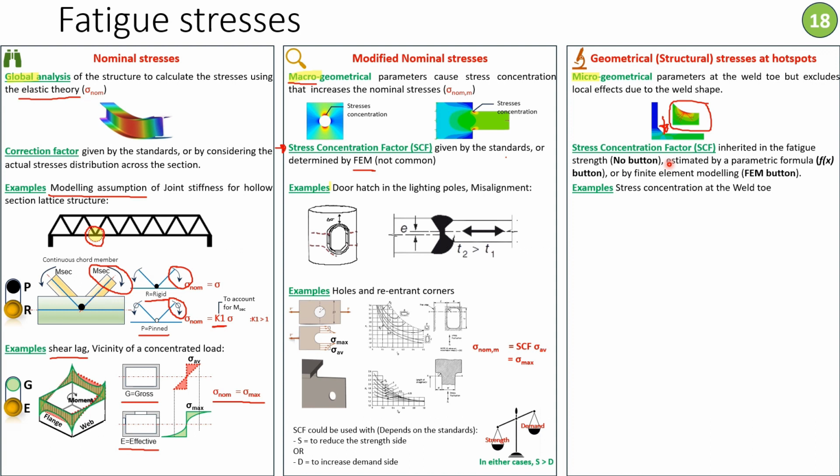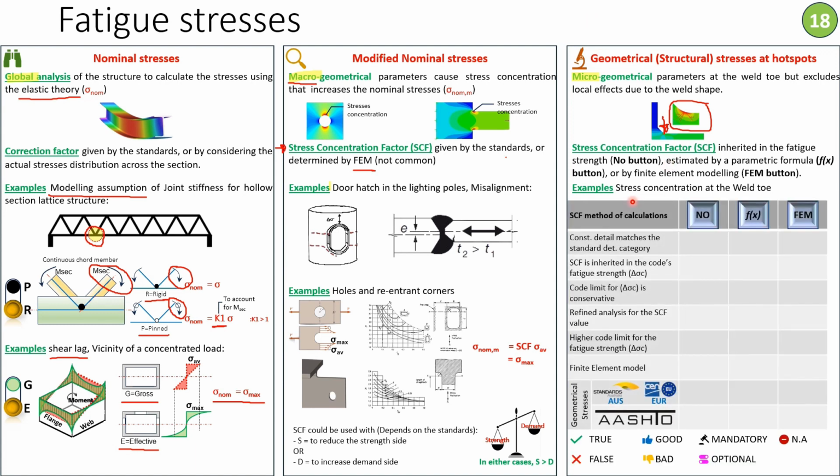Codes and standards provide the designer with a value for the fatigue strength. This value is based on testing for a range of plate thicknesses and member sizes. Hence, your connection might fit within the testing range conducted by the code, or it could fall out of that range. With this in mind, let's talk about the methods of calculating the stress concentration factors at hotspots or weld toes.